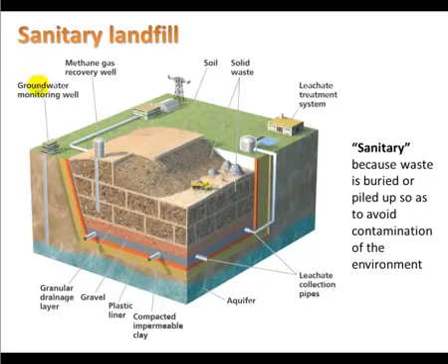And then ultimately, what we hope to do is cover up our solid waste with soil. Actually, that is what we do. Each day they put a layer of waste and then they cover it with some soil, and then the next day put more waste, then cover it with soil. So you can see here how this structure is set up with the layers of solid waste separated by layers of soil.